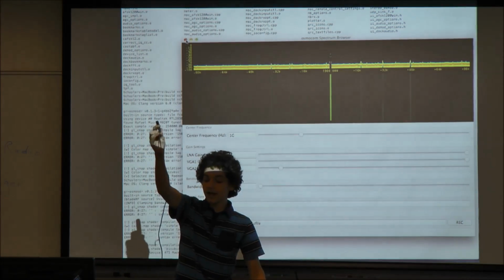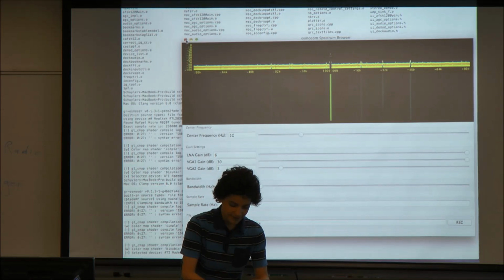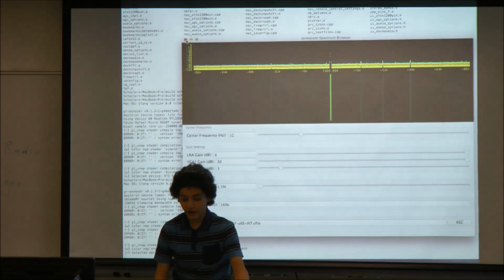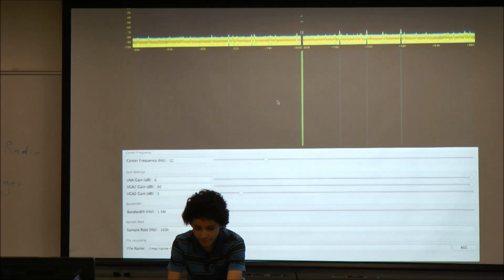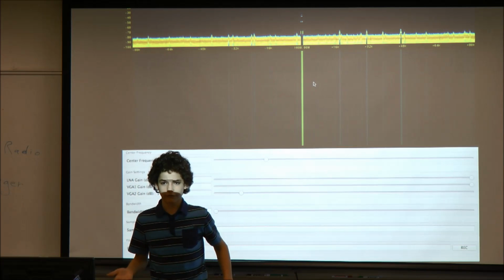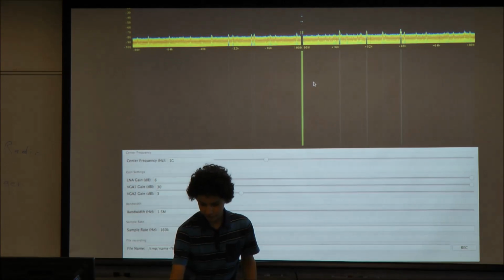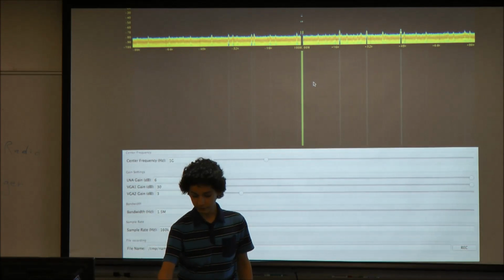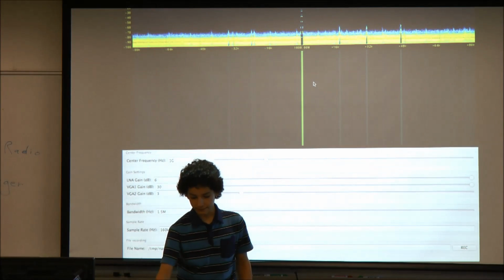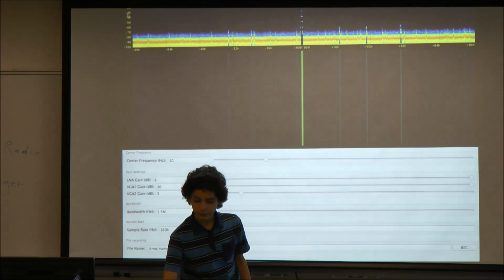One other thing, this cable acts as a giant antenna, so this will radiate more noise. But for this, I'm not doing fancy RF measurement, so it doesn't matter. So here's the Osmocom FFT spectrum browser with phosphor. If you press Q, you can move the separation. Arrow keys will change the gain and the position of, so this signal's in decibels.